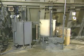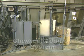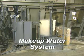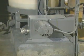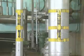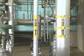Two additional systems are normally associated with the condensate and feed water system. They are a chemical addition system and a make-up water system. The chemical addition system may be connected to the condensate system, the feedwater system, or both. It generally includes pumps and associated equipment for adding chemicals such as hydrazine to prevent corrosion and ammonia to control pH. The make-up water system is connected to the main condenser's hot well.